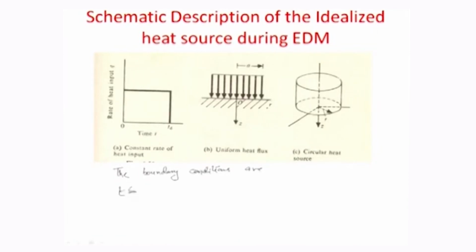that corresponding to time before the time of observation, that is at point of time 0 in our reference frame, we do not consider any temperature around the region. So, in fact theta, which is a function now of the radius, the depth and the time t, is considered to be equal to room temperature. In this case we consider room temperature to be in our reference frame 0 temperature.